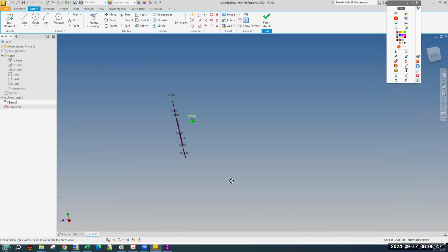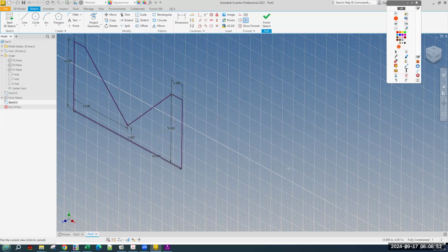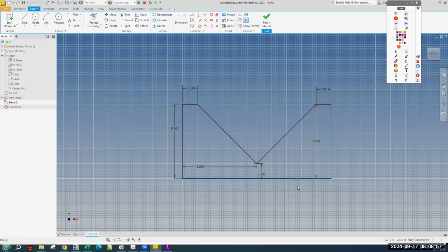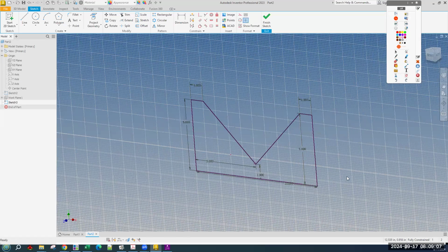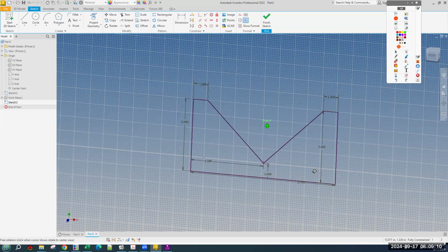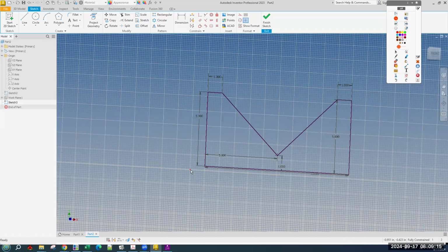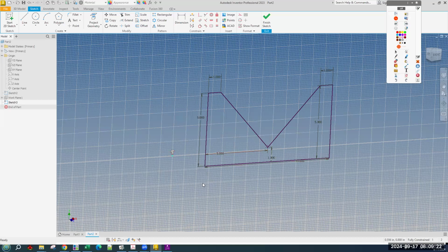Okay. So here's where we're going to draw the back. We're going to draw the back on this face. Now, the thing is, we need it to line up perfectly with the front. The bottom of the back needs to be exactly lined up with the bottom of the front so that it's flat. And the same thing for the sides. Now, we know that when we started the front, we started it from the origin point of where we started. So we could just do the same thing, but there's a shortcut.